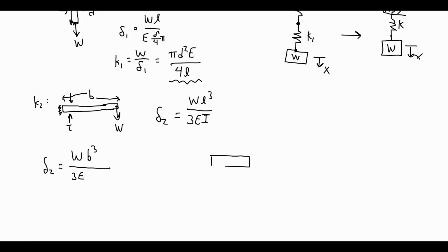Right, so if we recall, when we have a beam in transverse bending, we need to look at how the beam looks from this viewpoint. So I'm looking down the beam here. So I know it has a thickness of T and it has a width of A. So this is what I'm going to need to use to calculate the proper area moment of inertia. Right, so I need the area moment of inertia that is going to be calculated based on a horizontal neutral axis because that is the axis I'm going to be bending about.